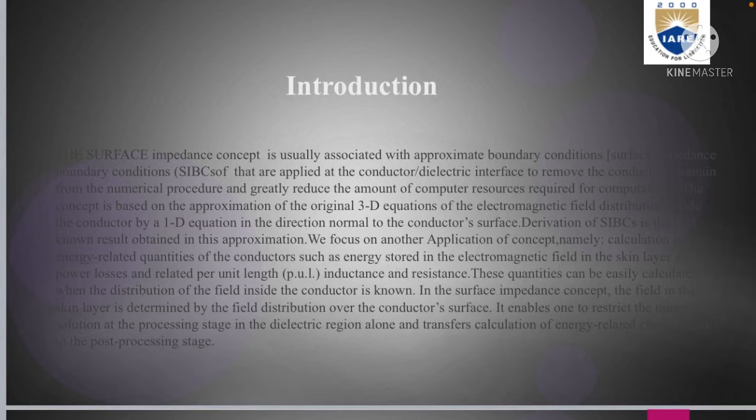The surface impedance concept is usually associated with the approximate boundary conditions. Surface impedance boundary conditions, SIBCs, are applied at the conductor or dielectric interface to remove the conducting domain from the numerical procedure and greatly reduce the amount of computer resources required for the computations.